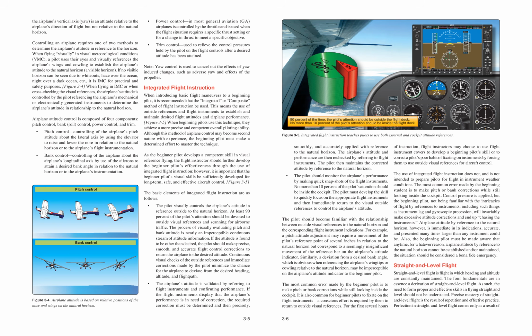The most common error made by the beginner pilot is to make pitch or bank corrections while still looking inside the cockpit. It is also common for beginner pilots to fixate on the flight instruments. A conscious effort is required by them to return to outside visual references. For the first several hours of instruction, flight instructors may choose to use flight instrument covers to develop a beginning pilot's skill or to correct a pilot's poor habit of fixating on instruments by forcing them to use outside visual references for aircraft control. The use of integrated flight instruction does not, and is not intended to, prepare pilots for flight in instrument weather conditions.